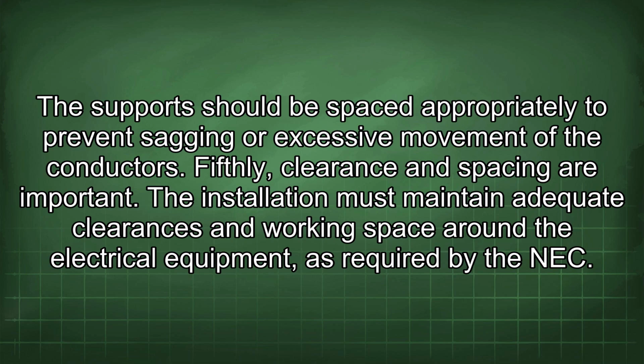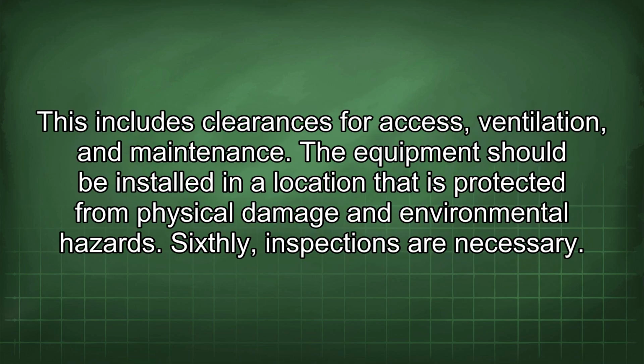Fifthly, clearance and spacing are important. The installation must maintain adequate clearances and working space around the electrical equipment as required by the NEC. This includes clearances for access, ventilation, and maintenance. The equipment should be installed in a location that is protected from physical damage and environmental hazards.